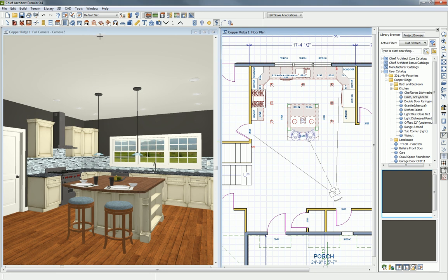So once we have our two switches, we can go back to our electrical tools to connect the electrical, and we can just rope these together. So very quickly it just snaps right to each of those fixtures. Connect that to our switch. Okay. Now these electrical connections that we've put into place, we can grab those and change their location and get your electrical plan dialed in.